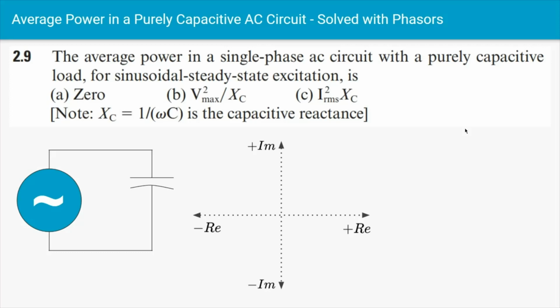Now, what does the impedance phasor look like? Well, that's going to be negative j, right, because it's a capacitor, divided by omega times the capacitance. And so to convert that rectangular form to a phasor, since we have minus j, you can think of it as just 0 in the real direction and minus j in the imaginary direction.